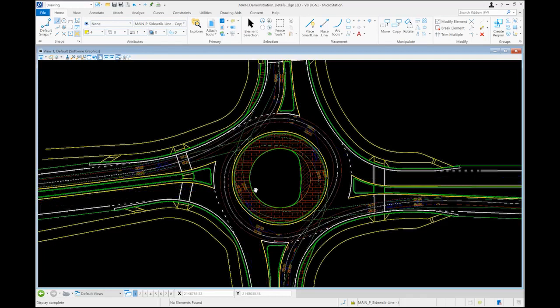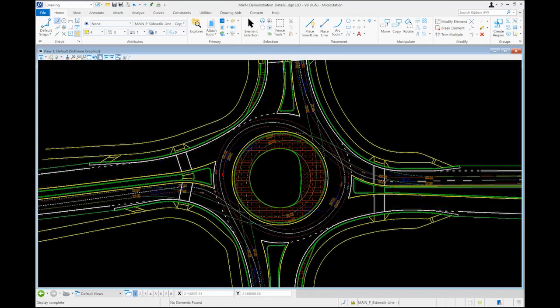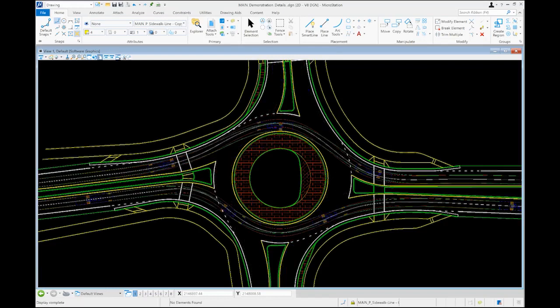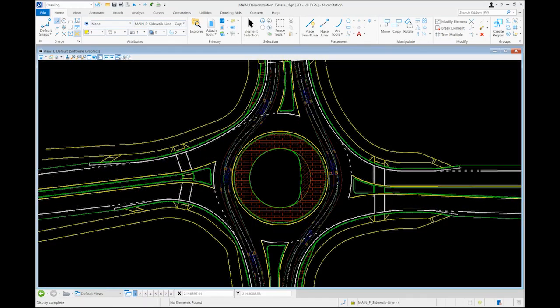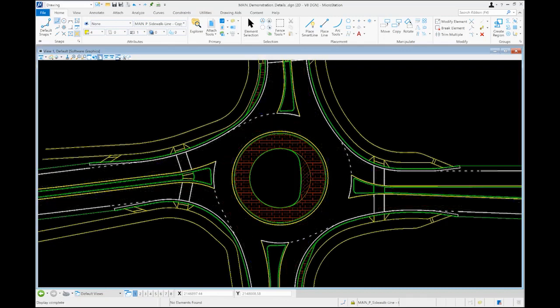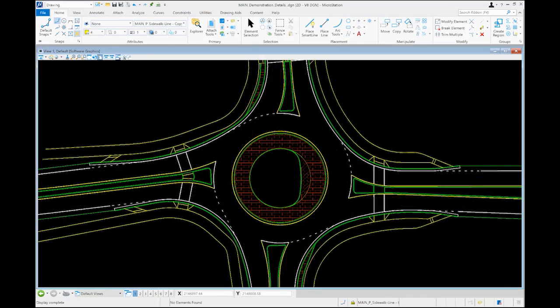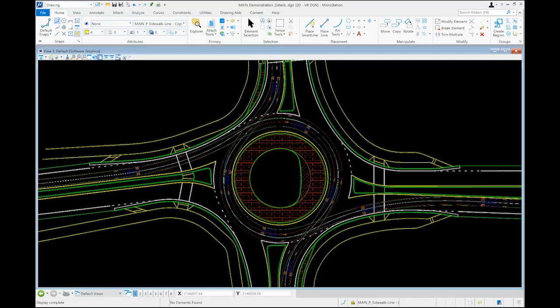So as we're getting into looking at these left turns around the central island, we have some areas here that are getting a little bit wider, that's needing a little bit more width in the through paths. The same in all the directions here. We've got some other vehicles that we're looking at in terms of bus vehicles in each direction to make sure that those buses, as they're going through, would not require the use of the truck apron within the central island.